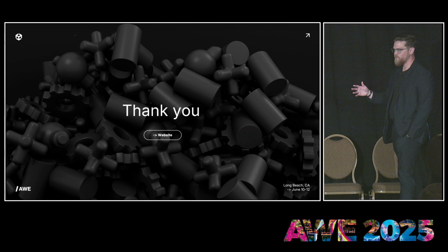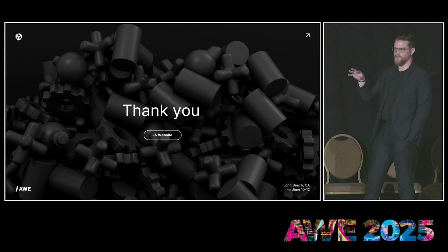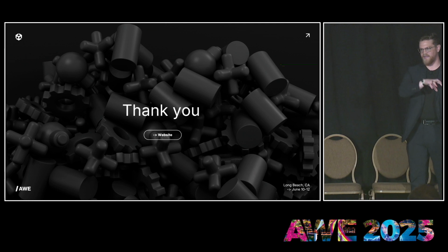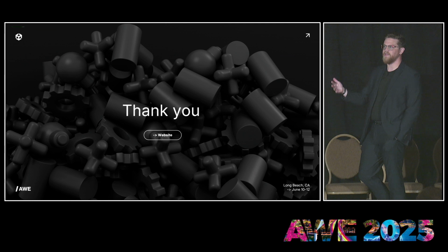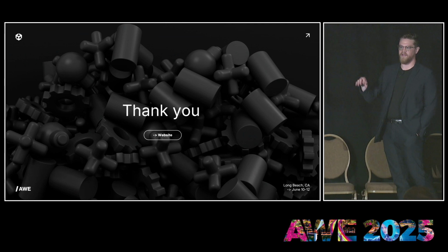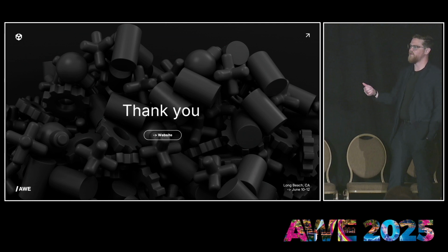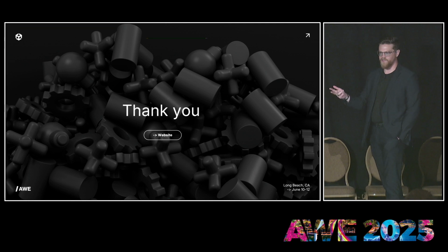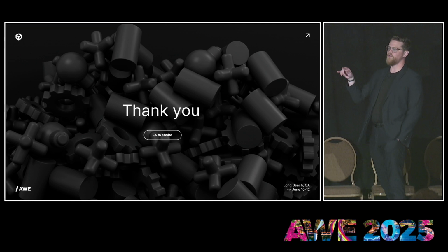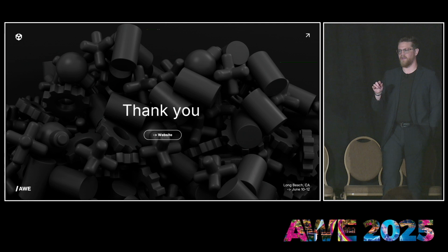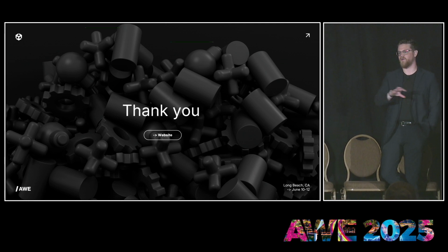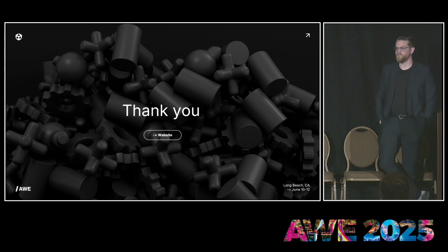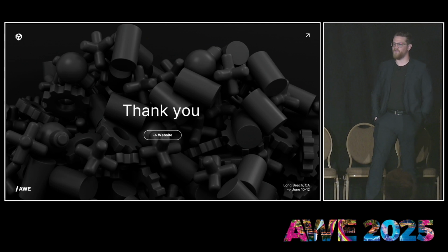Let's say you auto UV unwrap it. From Substance Painter, you could then push that file back up and have that override to a new version of the 3D asset, as well as have the textures pushed out. Let's say you're doing a Unity HDRP project, so you've done a Unity HDRP template. In that case, you would have your color map, your mask map, and one or two others that would be pushed out as well. You could push those up in the Asset Manager and create a dependency between those textures and the material and the 3D asset, so they would all stick together across your projects. Kind of like a prefab. Yeah, exactly. Works a lot like a prefab.